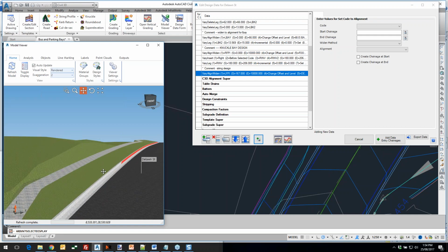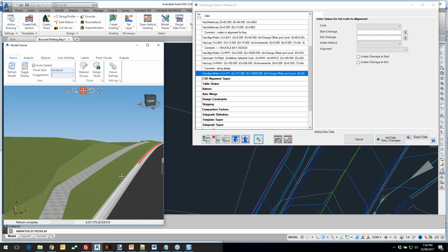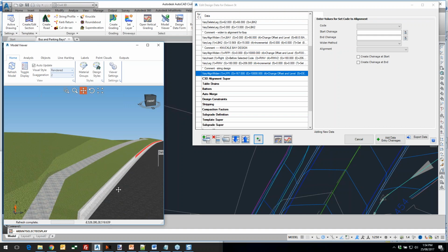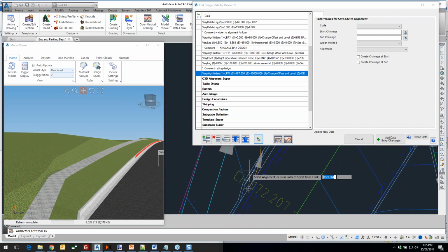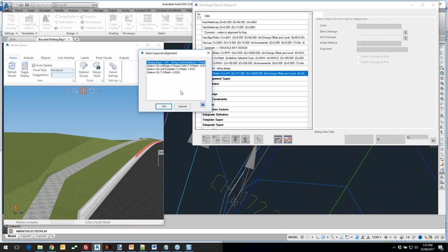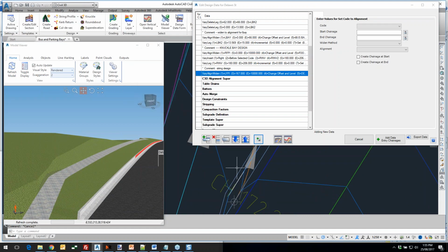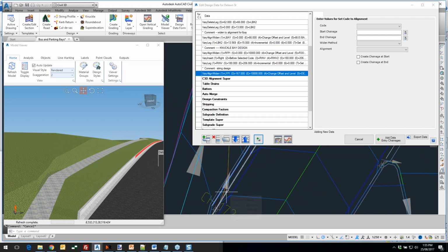Okay, so just to keep things neat for us more than anything else, we've pushed that out to make room for those bays. Okay, so this dish though, the back of that dish shouldn't exist everywhere. So you can actually see this first instance where the dish has gone in. Okay, so you can see that dish line. If I stop this command, you see that dish line's in there, and it cuts over the top of this alignment. So we're just going to sacrifice out the dish where it shouldn't be.